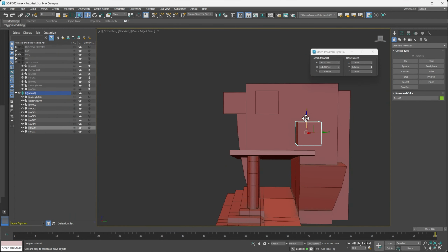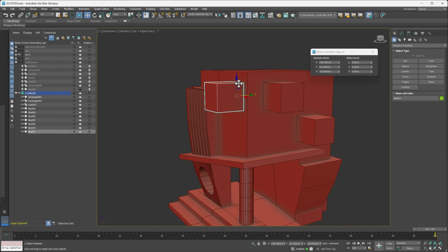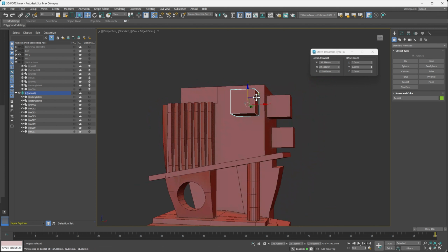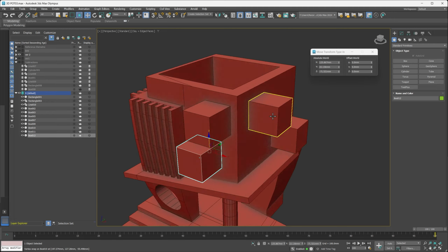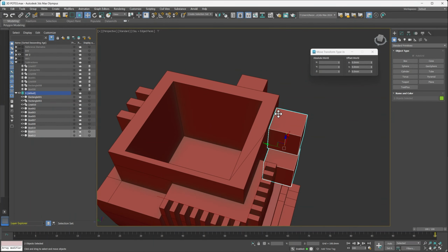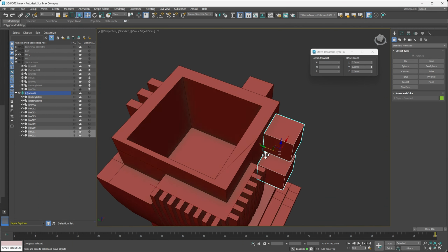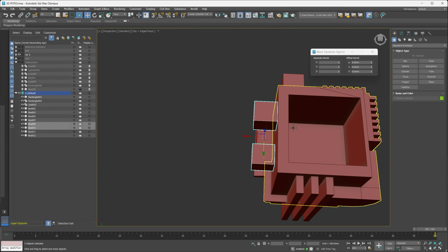All right, so they're kind of like floors, so let's keep them like relatively aligned. So I think this one here aligned with that one, and then we're gonna copy this down maybe, and we're gonna make this one here aligned with that one. All right, now we just need to move them to subtract them. So I think this is about 15 millimeters. So we're gonna go in about 5 millimeters. So 5, and these two here. So this is the x-axis. So we're gonna go -5.